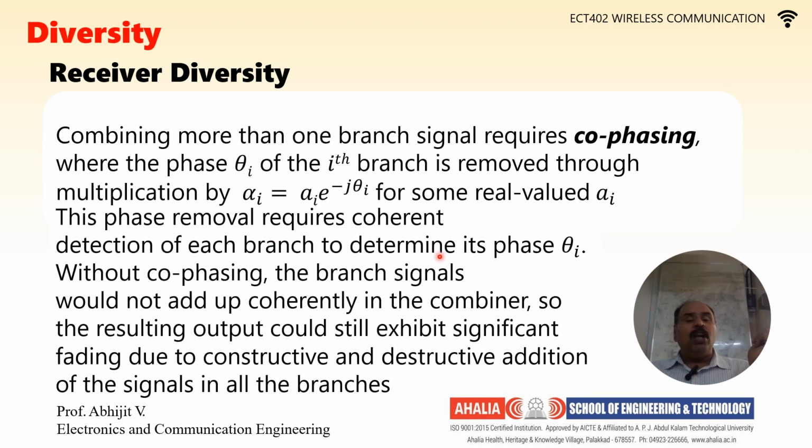The phase removal requires coherent detection of each branch to determine its phase. Without co-phasing, the branch signals would not add up coherently in the combiner, so the resulting output could still exhibit significant fading due to constructive and destructive addition of signals in all branches.